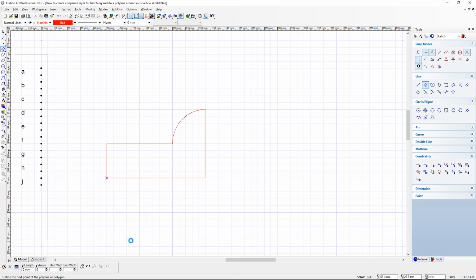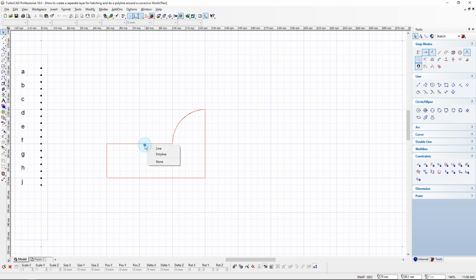And that will allow me now to hatch this layer, because if you are familiar with drawings, you will know that we hatch this layer if it is being cut. Now here in South Africa, what we do is that we always hatch our machine drawings at 45 degrees, and I know in most countries of the world that's the same practice. So what I'm going to do is use the selector tool, or the mouse pointer here at the top left of my icons, and I'm going to select that layer.